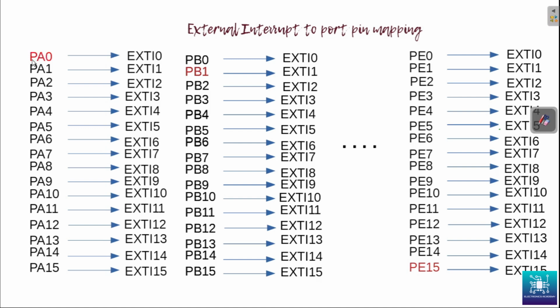If we have to trigger an interrupt by pushing the user button, without using any other external circuit connected to our eval board, the only option that remains is to have this logically connected to port A0 of the processor. So we will map EXTI0 to this.